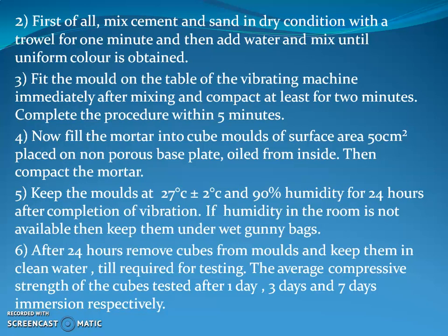If the humidity room is not available, then keep them under wet gunny bags. After 24 hours, remove cubes from the mold and keep them in clean water till required for testing. And the average compressive strength of the cubes is tested after 1 day, 3 days and 7 days of immersion respectively.